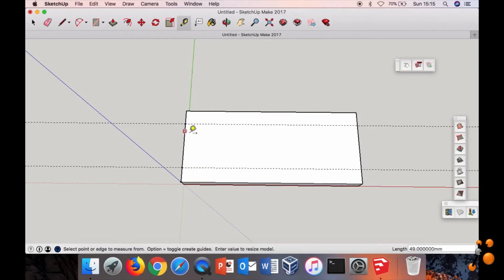Let's put a line, and then here we decide to put it thinner for the reason that I explained before. It is 2 millimeter. Okay, like this. Then so now we have 2 millimeter wall here, 4 millimeter here, and 4 millimeter. The LED will be inserted like this.